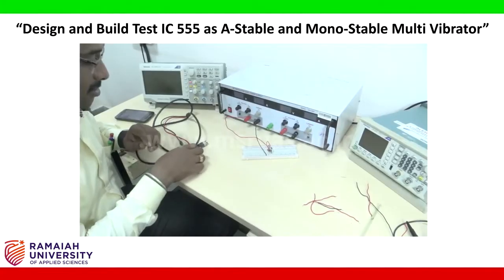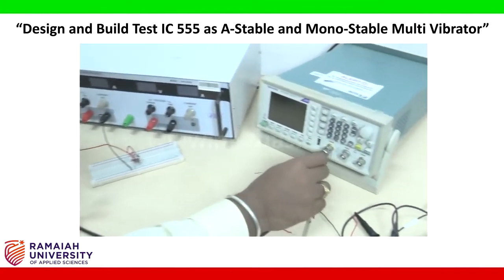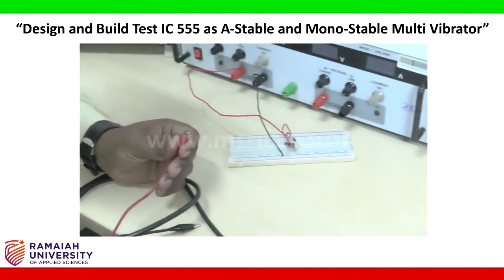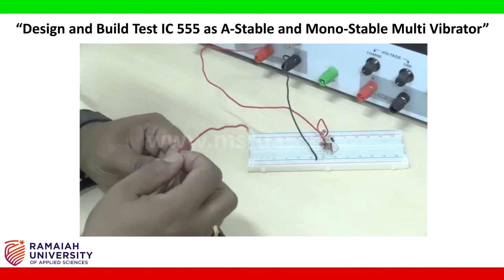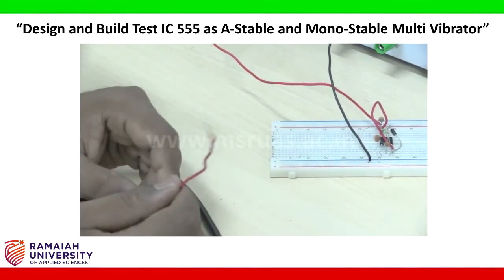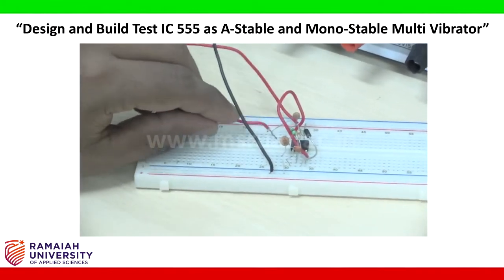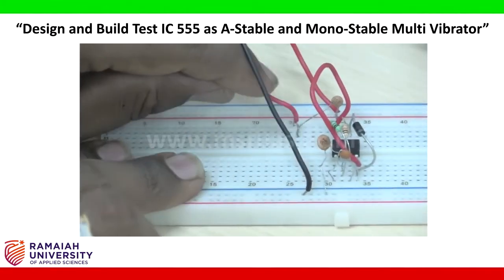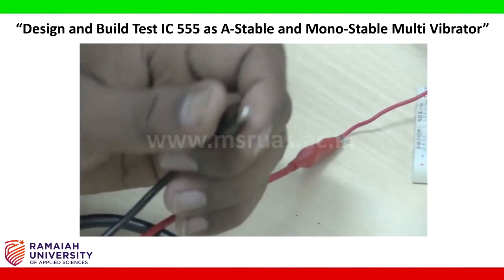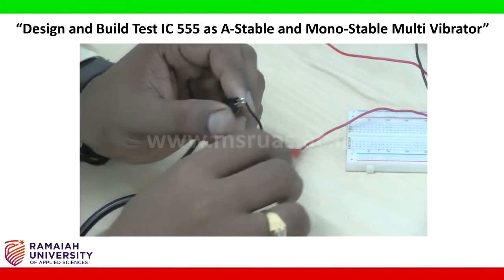Next, take the patch cord to connect the input from the signal generator. So this is the input of the signal generator terminal. The positive end will be connected to the capacitor, the one end which we are leaving free. So you connect that to this point. The negative you make into ground, for a ground connection.